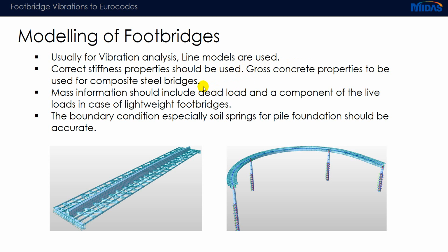We should include the dead loads and all superimposed dead loads as mass information for the vibration analysis. And for lightweight footbridges, we should make sure that a component of the live load is also considered as a mass. Another important thing to ensure is that the model has been defined with the correct boundary conditions. So whenever we have soil springs or we want to model soil structure interaction for pile foundations, it should be very accurate. So I'll just quickly run through some of the models that we are going to look at today.